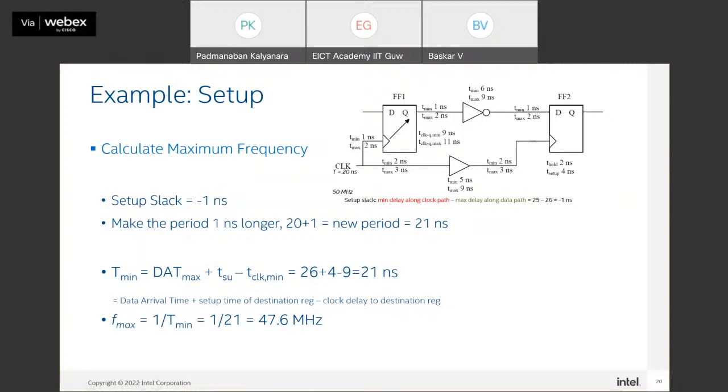If you increase the clock period, there would definitely be an impact on the frequency. It is also very important to understand that this is not a desirable option, because there are multiple techniques that could be used to overcome setup violation, whereas increasing the clock period is always an undesirable option. After entering the timing analyzer tool, we will identify what other techniques could be adopted.